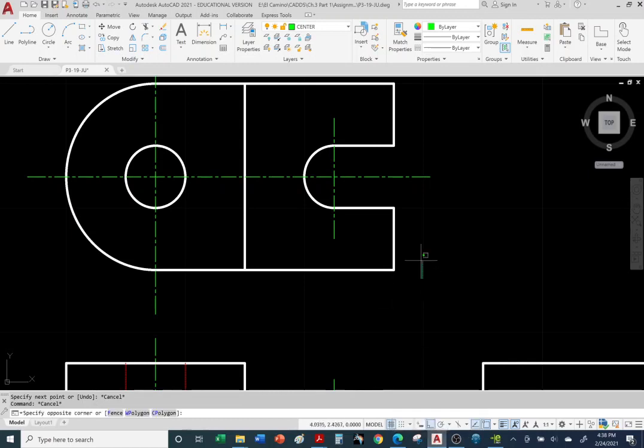By the way, if you were to create a center line, let me turn off ortho temporarily. If your center line looks like this, that is incorrect, right? It's supposed to be vertical. So if you drew your center line like that, that tells me this student forgot to turn on ortho and created a vertical line that's skewed. It's not a vertical line. So this is incorrect, and you have to go back and fix it. I will take points off if your lines are not vertical or horizontal as they're supposed to be, right? So you would have to fix this.